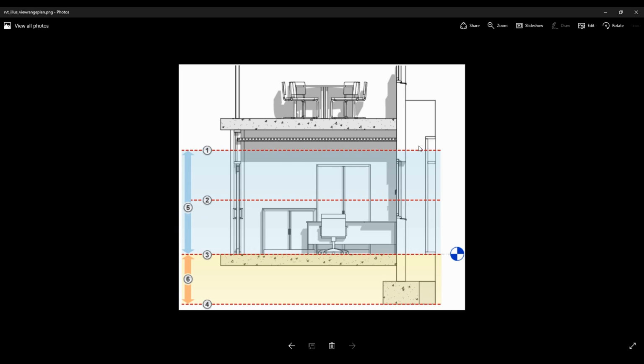This up here is your top view. So any mechanical elements above here, above your cut plane, won't show, I believe. I'll have to confirm that. Maybe, I think they do actually. Sorry, I'm getting confused. Any architectural elements such as windows and doors and stuff, they won't show up if they're above this cut plane. So if you have like a clear story right here or something, it won't show up. You won't be able to see it on the plan view.